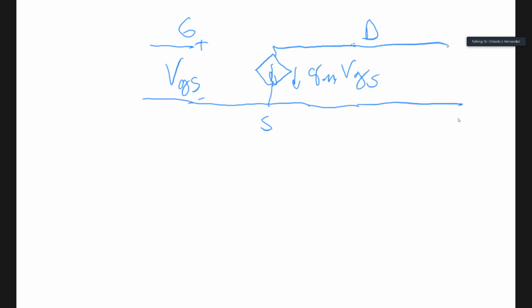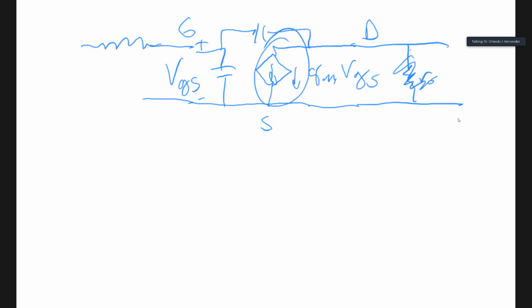The next up is when you have an output resistance for the transistor, and we're saying that we're going to neglect that, so it's high enough that we can say it's not there. Okay, but imagine, as you are doing more and more things, you need to make this model more complex. You can add a gate capacitance, you can add a gate to drain capacitance, and if you're doing microwave stuff, you can start adding inductors and all kinds of things, right? But for us, it's going to be just that GM. Okay, that's what is meant there.